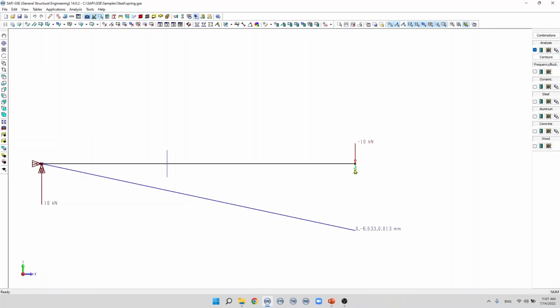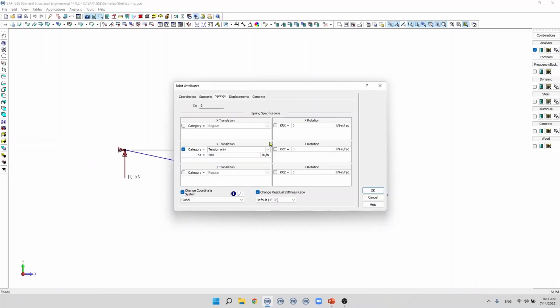In this case, if we remove the spring completely, we will obtain the same results because the spring is already deactivated. We also have springs that act as one-way elements, which are limited to compression and tension. In this case, we need to specify the maximum force that the spring can support. So, the behavior of limited compression springs and limited tension springs are similar to compression-only and tension-only springs.